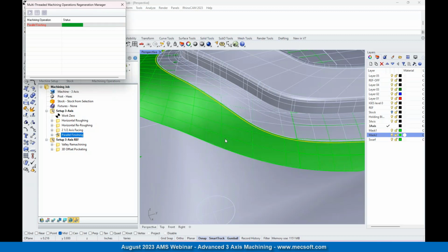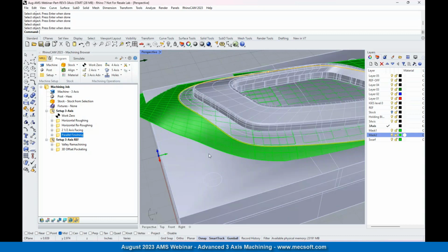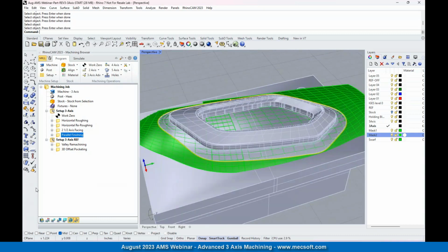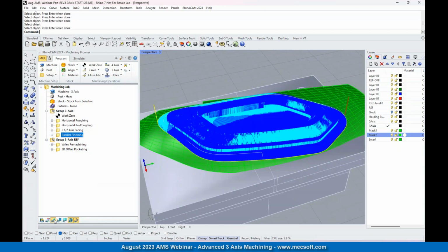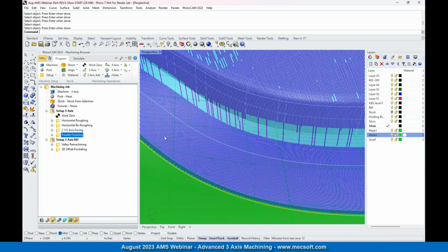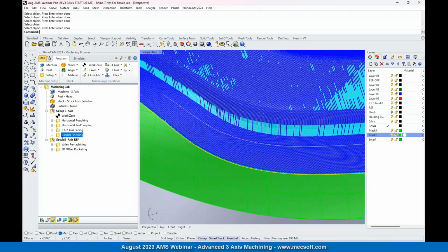Well, one of the things I wanted to point out is Don always sets the arc fitting tolerance to twice that of the machining tolerance, if you've noticed. And that's one of the best practices. We let all our customers know. So that's a very good practice to have. So always make sure that the arc fitting tolerance is actually at least double that of the actual machining tolerance.